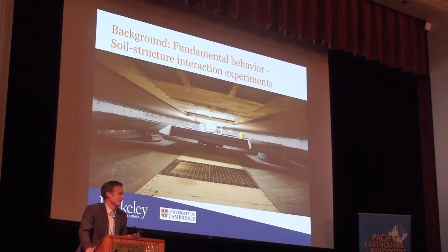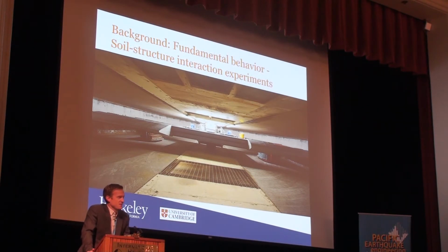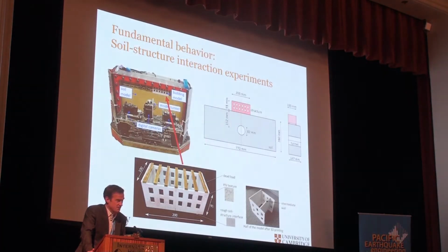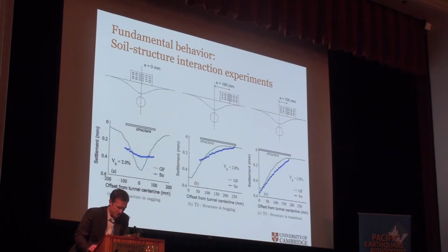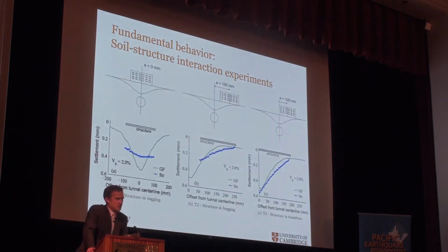First, a few words on background. I spent a long time on this project in Cambridge looking at the effect of settlement on structures due to excavation. We did several centrifuge experiments on this. If you're interested, I could refer you to those papers. Essentially, here's the experiment: we build mini buildings in the centrifuge, we simulate contraction or settlement of the soil, and then we can measure in pretty good detail the deformation of the building itself.